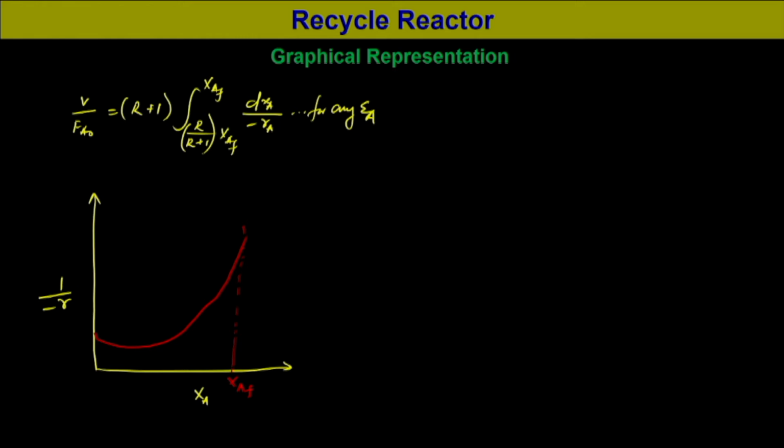Now, if it is a plug flow reactor, this is the integral term of the performance equation of the recycle reactor. In that case the limit is from R by R plus 1 XAF to XAF.